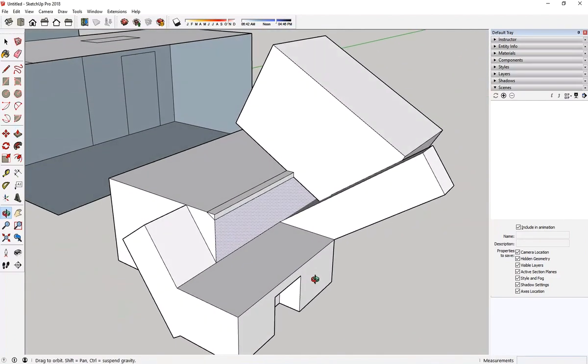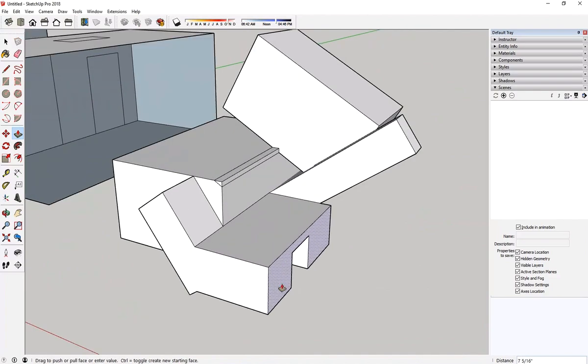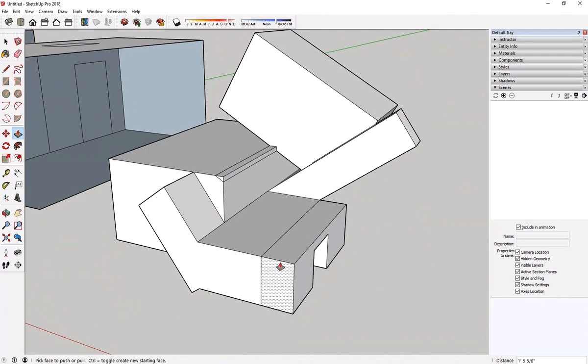Now I have created this surface down here, so I can work with that surface. The other thing that I can do when I'm working with push and pull tool is that if I hold Control and use the same push and pull tool, you can see that it shows a plus sign there. If I click on the surface, now when I push and pull this surface, that actually adds additional surfaces on that side. What does that mean? That means that I can now have multiple surfaces. So I know where I started, and that becomes very helpful, especially with editing a geometry, or when you are trying to conceptualize your work.